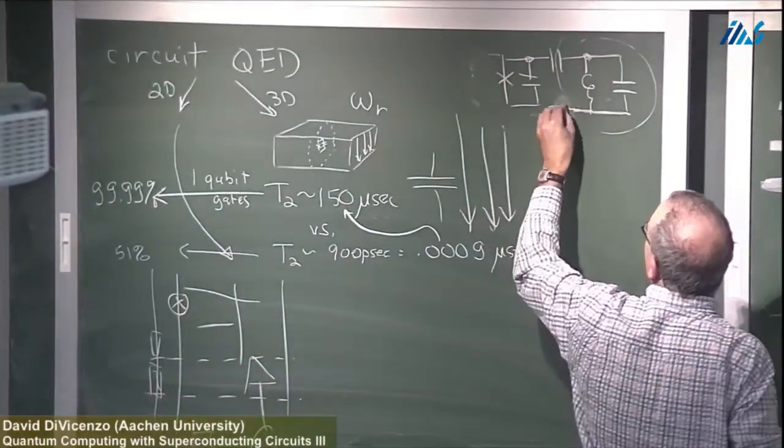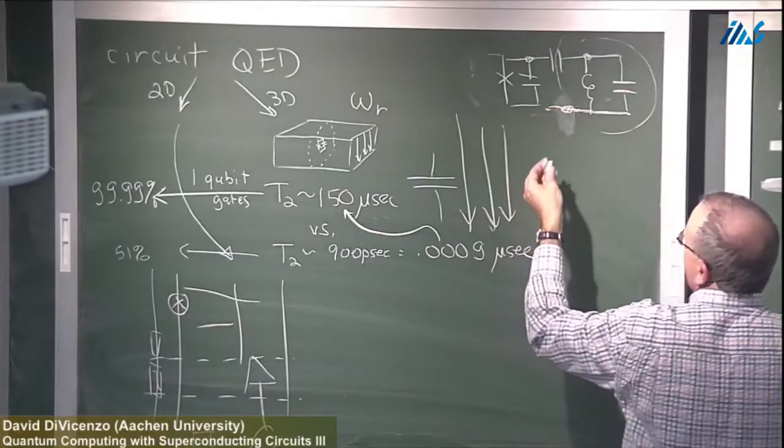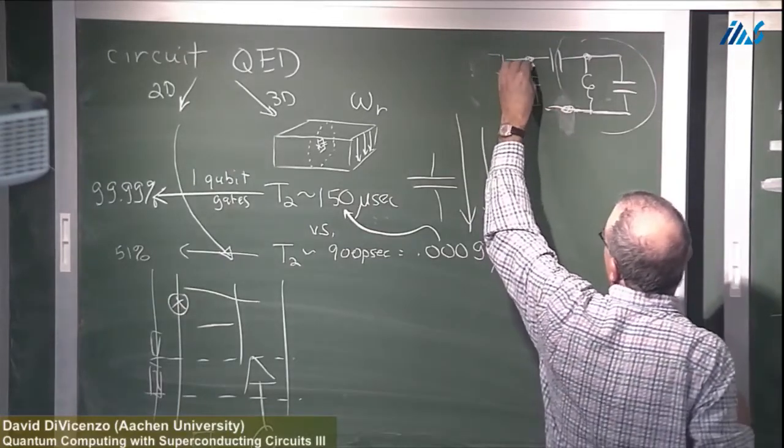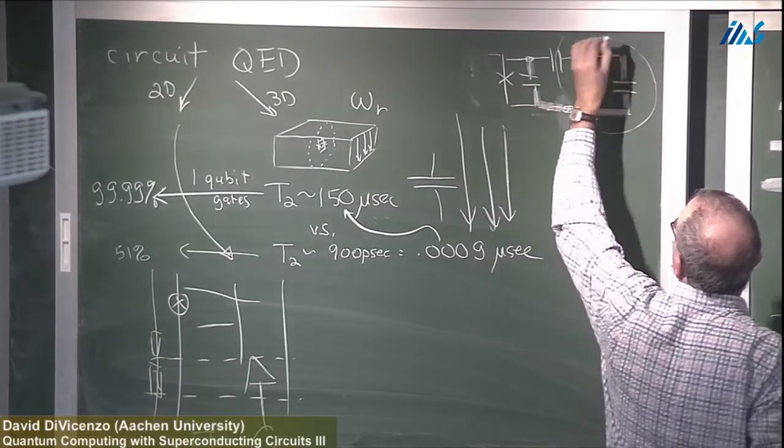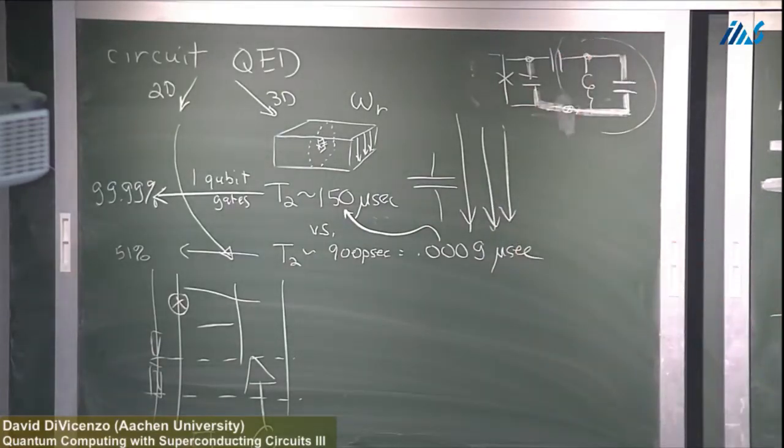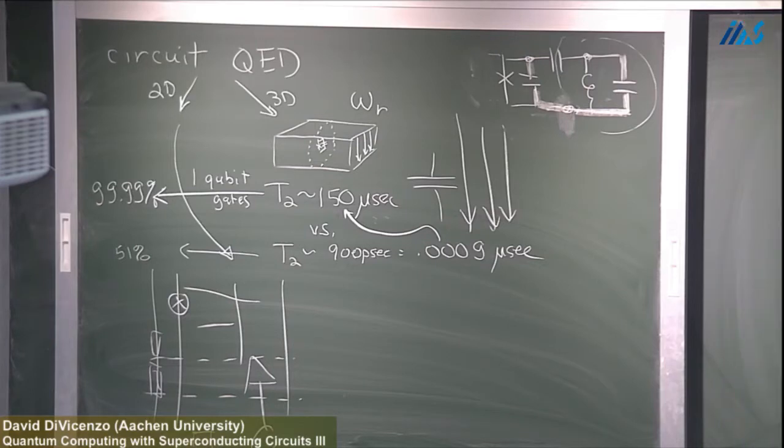This is a 3-node circuit. So this is the graph theory of it. And it has a spanning tree, which can be taken just to be these two capacitors. And so it should have, and it does in fact have, two canonical coordinates when you write the Hamiltonian. And let's write it. Put it here.